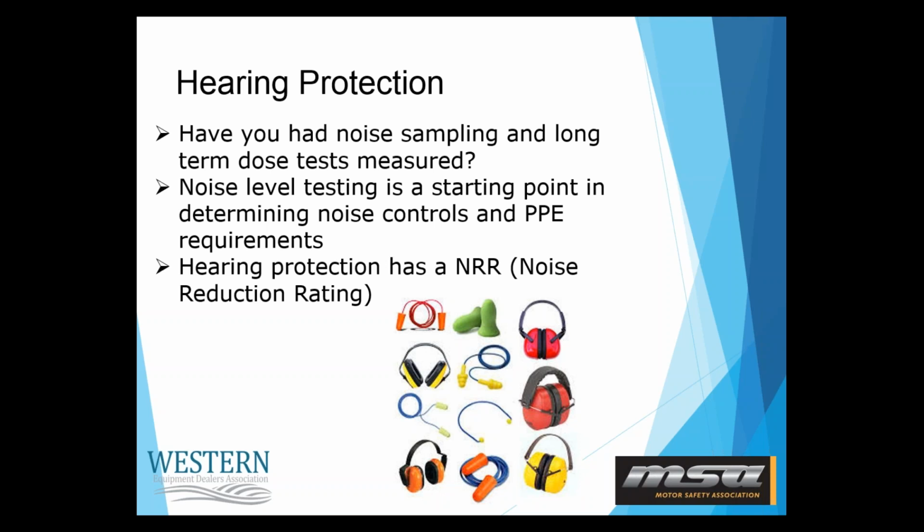So if they're using tools such as shop vacuum, pressure washer, impact wrenches, we can do a sample right at the worker's level. And then we also have a long-term dose meter, which provides us with that 8-hour sample. And that's something the worker would wear in their pocket, which would give us that LEX value of the exposure level for the worker.